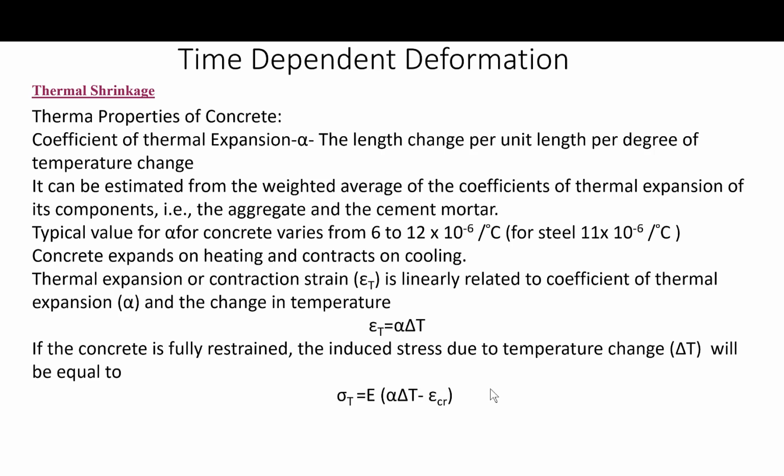So the resultant compressive stress will be small and usually does not really cause any problem. However, when the concrete cools down to the ambient temperature from its peak temperature, the temperature drop will cause thermal shrinkage and may induce a tensile stress in the concrete. Okay, that's really something that you need to worry about. So in mass concrete, the difference between the peak temperature of the concrete and the ambient temperature could be very large, and the temperature drop could induce tensile stress to cause thermal cracking of concrete. And this is something that you really have to watch out for.